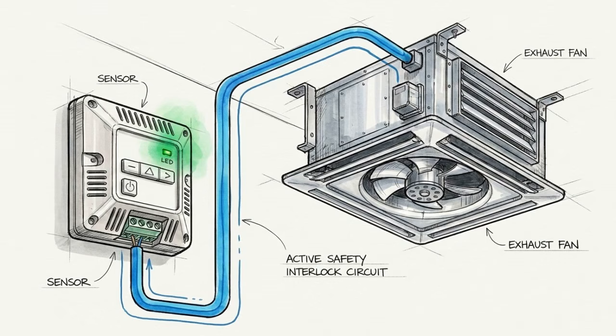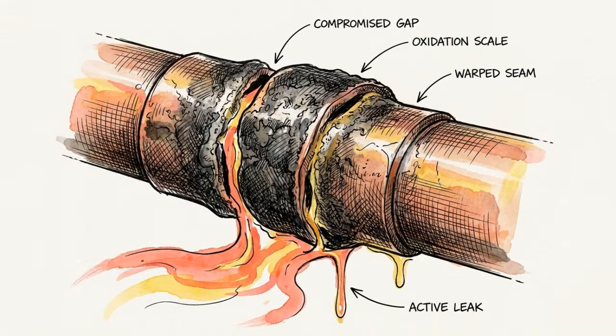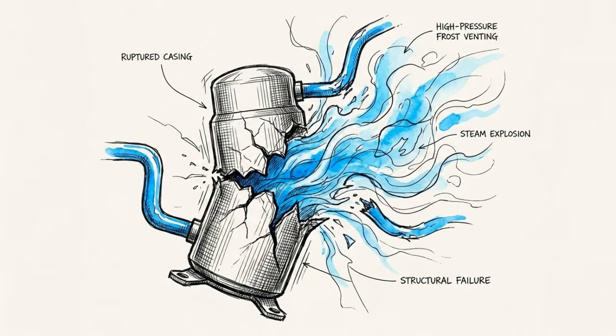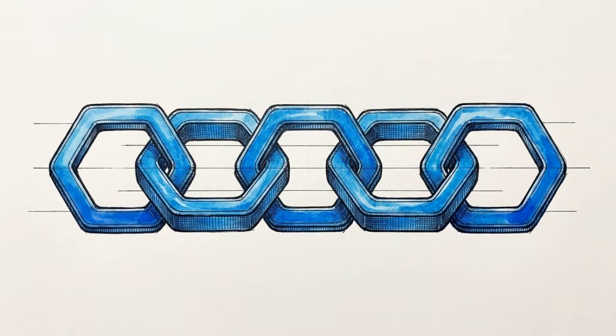This often requires localized concentration monitoring linked to mechanical ventilation interlocks. Without rigorous installation discipline and strict volumetric safety calculations, the underlying physics of the refrigerant cycle will eventually defeat the mechanical design. To prove the design works, facilities execute a sequential commissioning proof chain.